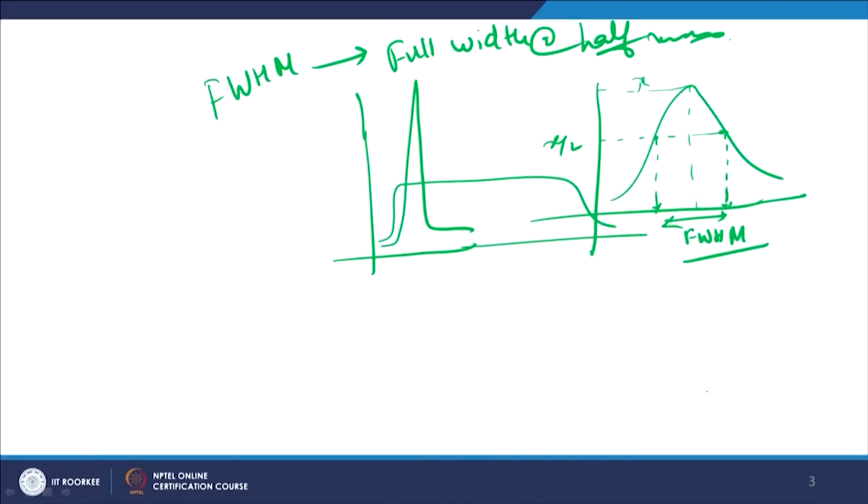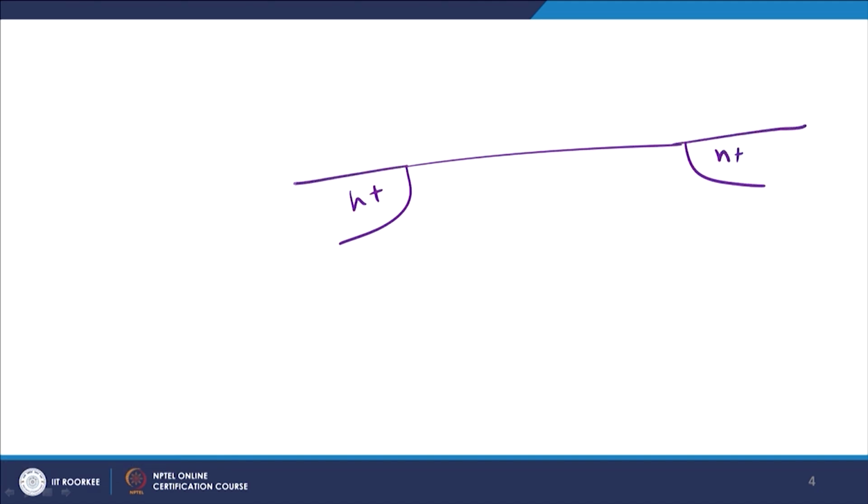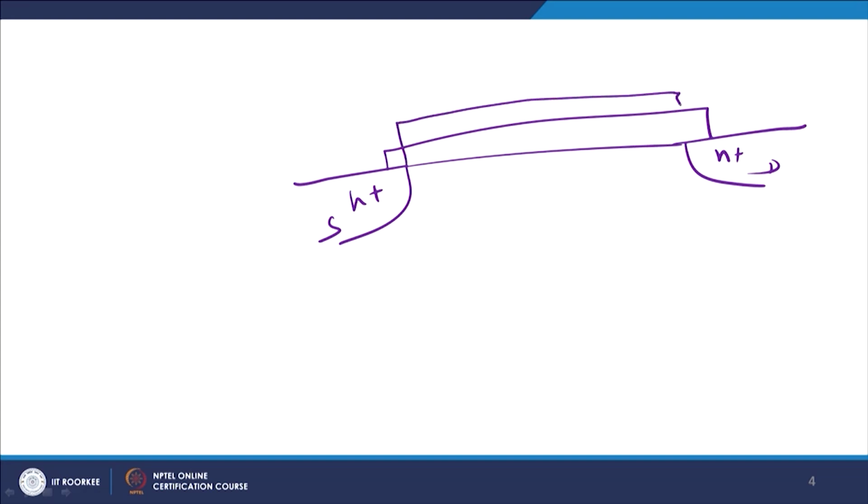An important point in current technology is that you require self aligned processes. Self aligned primarily means that, suppose you have a device which is something like this, this is your n and this is your p, n plus and n plus, and this is your source and drain, right. If there is overlap, then you are overlapping with it. Self aligned means that the alignment of the oxide and the metal is exactly that of the source and drain material, and that is how you do it here.